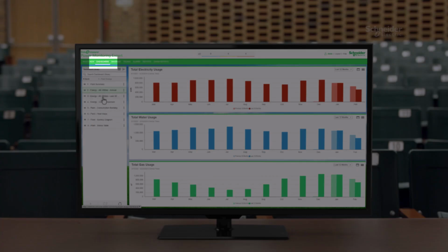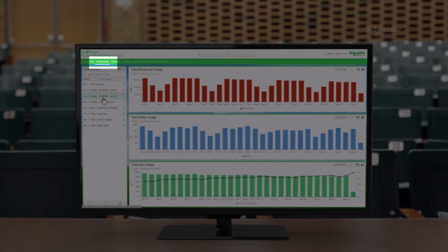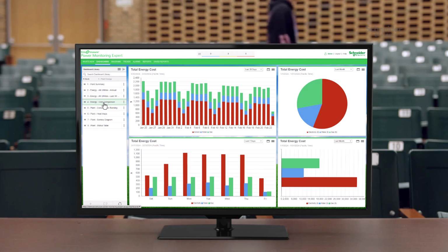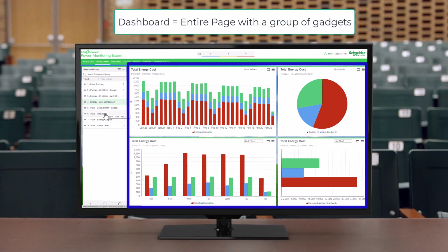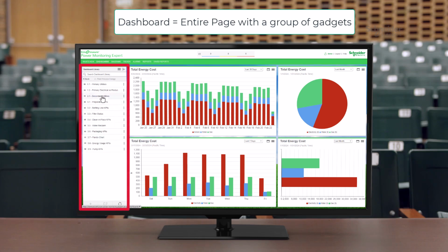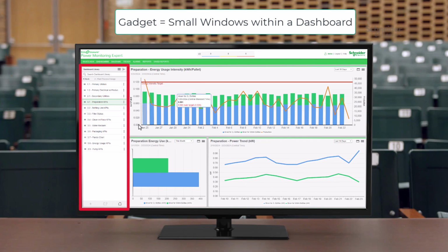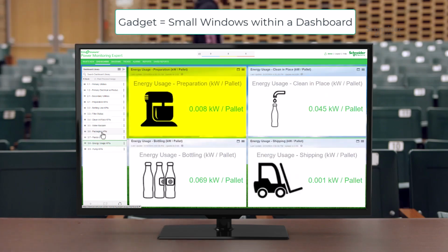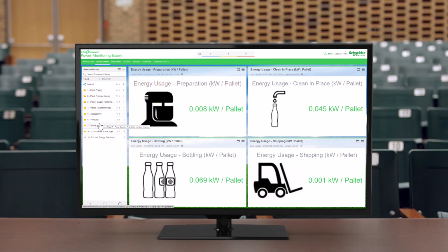Dashboards is an application to view high-level historical and real-time data, for example key performance indicators, KPIs. The information in the Dashboards application is accessed through Dashboards with Gadgets. Dashboards are saved in the Dashboard library. Gadgets are graphical display objects used in the dashboard display pane, for charting trends over time, or in comparison with correlated measurements or similar functionality. The gadgets available for a dashboard are listed in the Gadget Setup dialog, which opens when you click Add Gadget in the Dashboard Controls area.